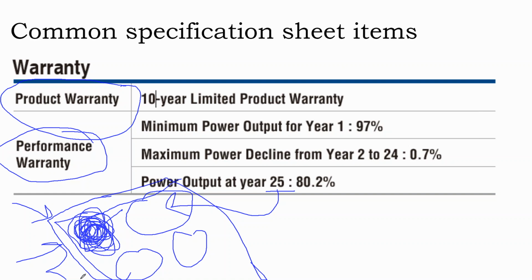How the panel is handled from the time it leaves the factory to the time it's put on the roof, and then furthermore, how the system is designed and installed: a hurricane zone versus a non-hurricane zone, an environment that has severe temperature extremes versus one that doesn't, a saltwater environment versus a freshwater one, a farming facility versus a standard rooftop, where the clamping zones, if they were properly adhered to or not. All of those things can add up to result in a system failure that doesn't have anything to do with the module cell itself.